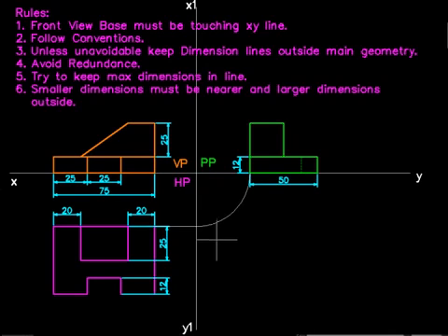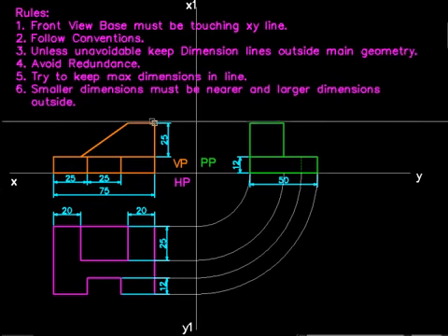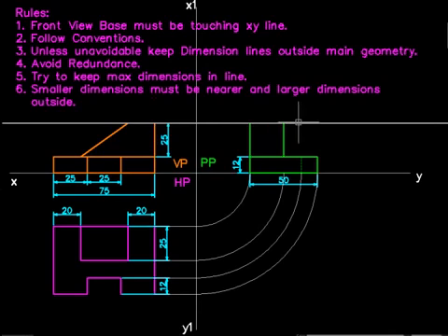Similarly, we have to take these lines from the different points, from all these points, from this point as well. So similarly, an arc also has to be drawn from all these points. And once you draw the arc, these points must be used here to get this side view. So even the side view is going to be matching exactly with the horizontal line from here. So this should be of the same height. Once you take the dimension here, you don't have to take the dimension again on this side. We can directly use projection lines in order to make the side view.